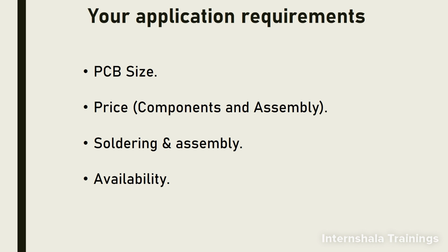Also, the price of the components could be a very important aspect. Since resistors themselves are not so expensive, the assembly for THT components is higher compared to SMD components for mass production. But for small quantities, SMD is a bit harder to solder compared to THT components, if you want to solder them by yourself using a soldering iron, for example.